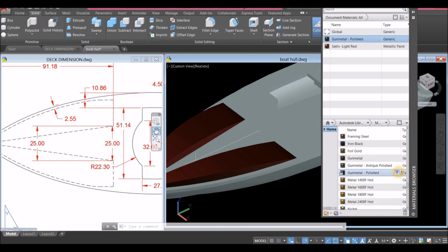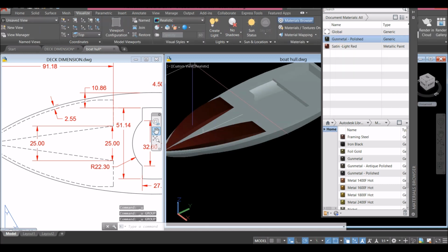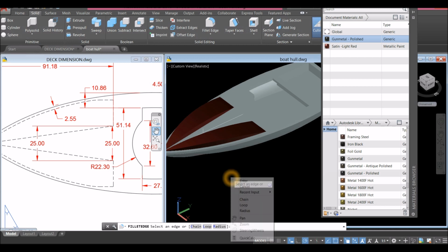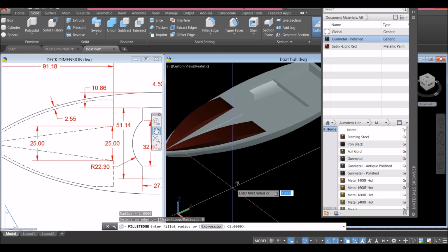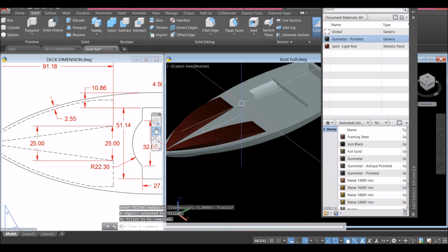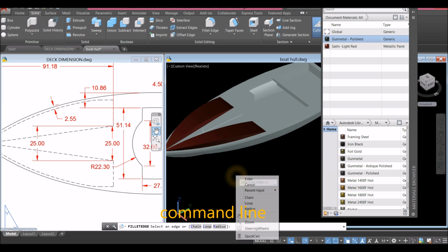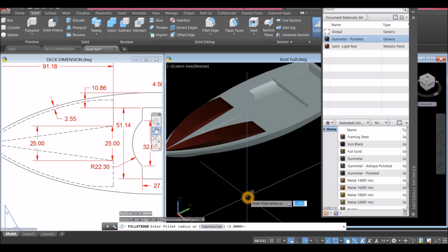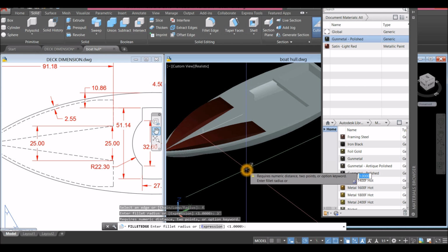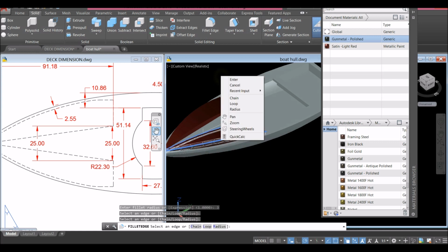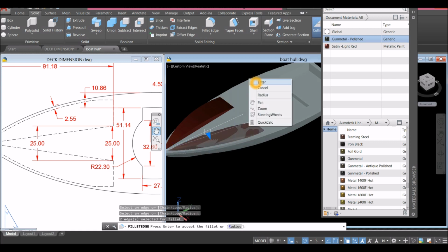maybe this one here. All right, I have to apply, go to solid, apply fillet edge, right click and select radius option, or you can go down to the, okay, I'll show you again. Fillet edge, you can go down to the status bar, there's a radius option, you can click that, or you can right click and select radius and enter 3, and select this edge and this edge, enter and enter again to accept.